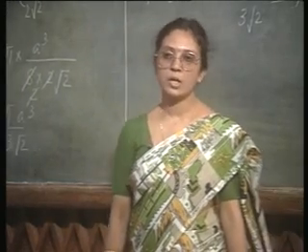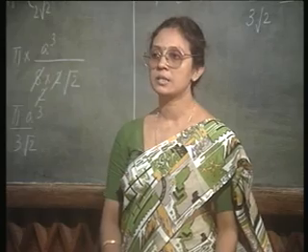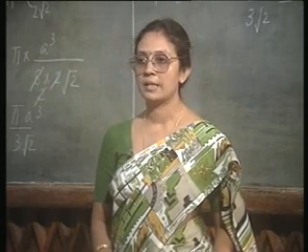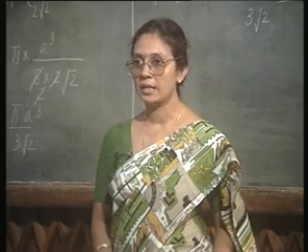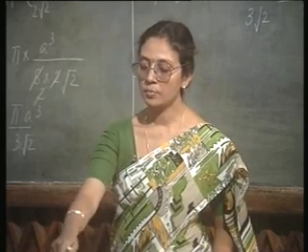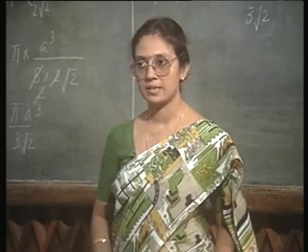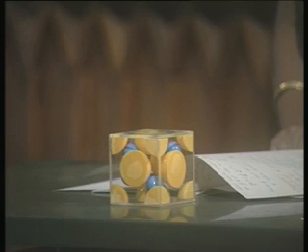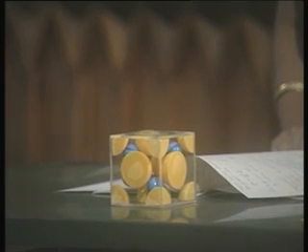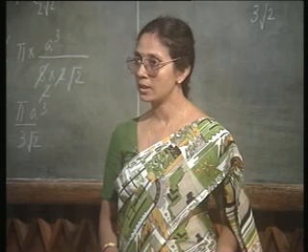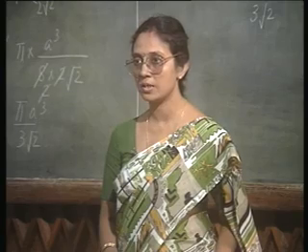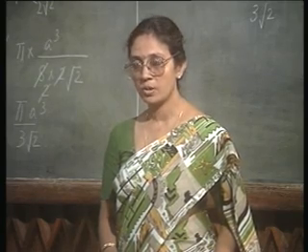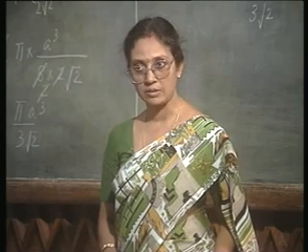Suppose you are introducing impurity atoms inside silicon. They will be electronically active only when they have occupied the proper positions in the lattice, that is, when they have substituted for silicon. Otherwise, most likely they will not be electronically active. They might be precipitated, they might stay in the interstitial points. So, they will not be electronically active.